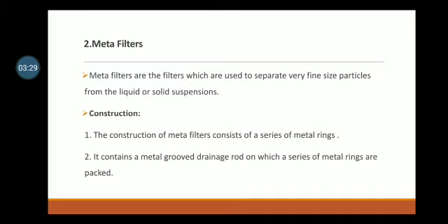Then second, meta filters. Meta filters are the filters which are used to separate very fine sized particles from the liquid or solid suspensions. Construction: the construction of meta filters consists of a series of metal rings. It contains a metal grooved drainage rod on which a series of metal rings are packed.